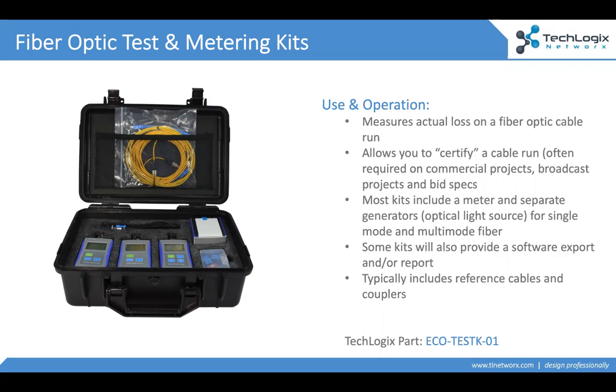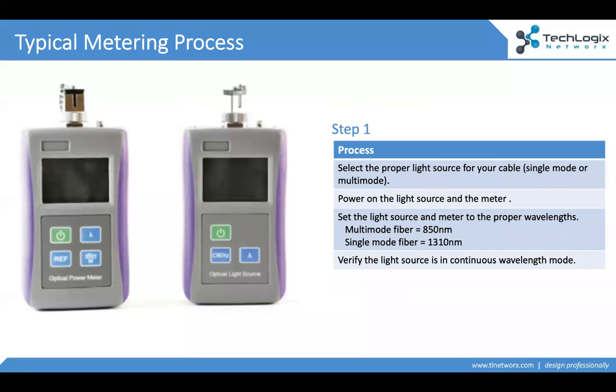Now, there are a couple of things that are important here because people who buy meters, they look at it and they say, okay, look, I'm just going to plug these meters into both ends of my cable run. While you can do that, it's usually not recommended. We recommend that you use reference cables, and we'll talk through that here in a minute, because those are wear components. Those are components that get dirty and can be replaced. And that's going to allow you to really maintain that trunk cable, that main cable that you've pulled, keep it as clean as possible over time.